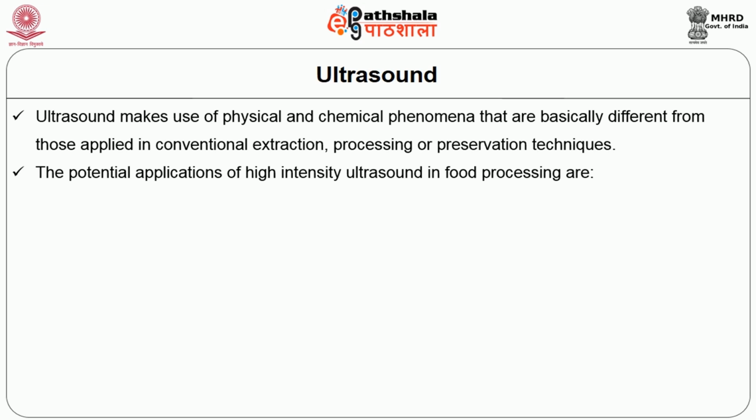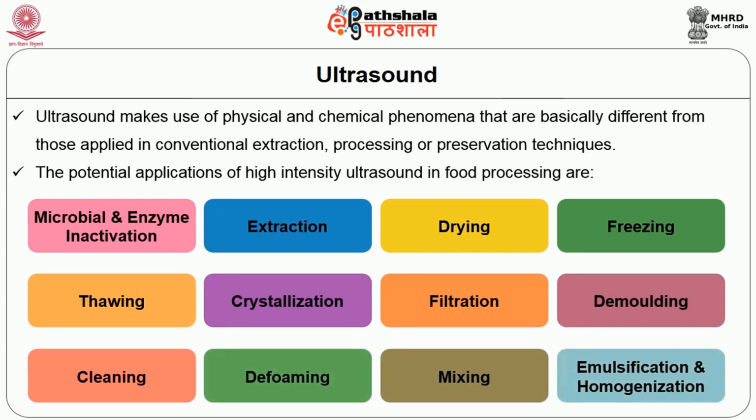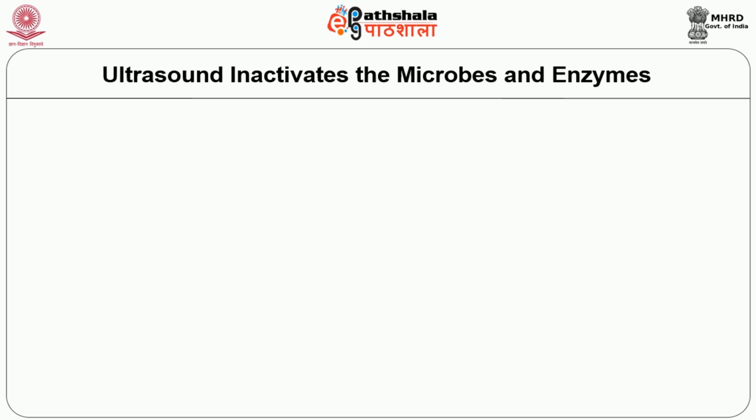The potential applications of high-intensity ultrasound in food processing are microbial and enzyme inactivation, extraction, drying, freezing, thawing, crystallization, filtration, demolding, cleaning, degassing or defoaming, cutting, mixing, emulsification and homogenization. Let us now see how ultrasound inactivates the microbes and enzymes.